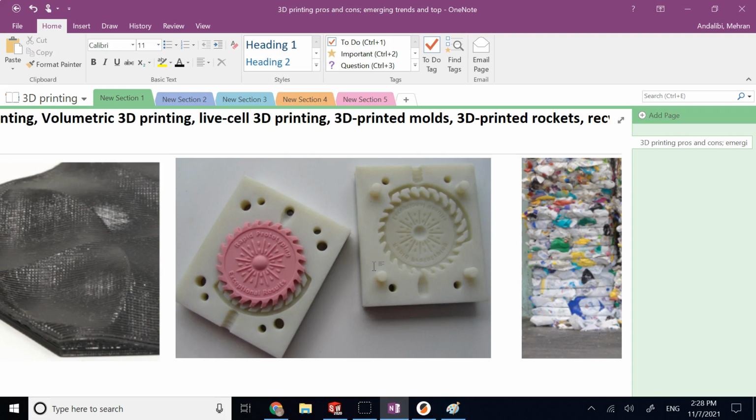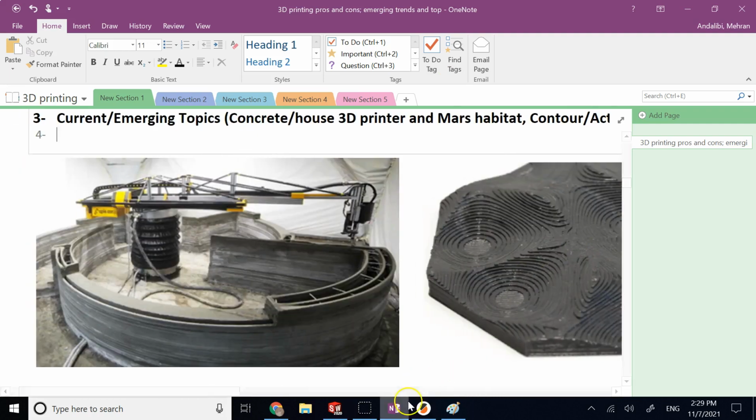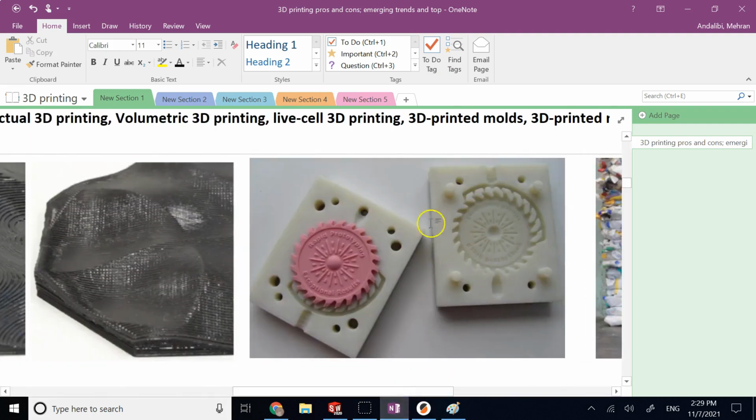So now they are trying to make the molds for many plastic parts out of other plastics. And how do they do that? By 3D printing them. So now they are trying to 3D print molds. And here you can see these two white parts that are molds for this purple part. They are 3D printed out of a resin, and that resin has a quite higher temperature tolerance than the actual plastic of the material, this purple one.